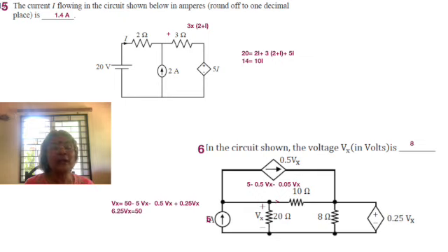Okay, so now what happens? What is required out of it? Of course, there are other resistors. Unlike the 8 ohms, there is a 10 ohm resistor as also a 20 ohm resistor across Vx, which tells us that there is a current through it. Since the upper terminal is positive, the current is entering the 20 ohms from the top, and that's equal to Vx by 20. What is required out of us is, in the circuit shown, the voltage Vx. So we need to find out Vx.